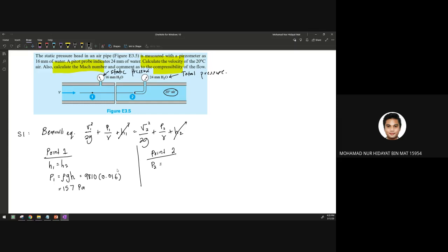So remember that this is a pitot tube meter. When it is a pitot, there is a stagnation at this point. I try to zoom in. This is the tube. Basically the tube is like this. So the water going in this direction suddenly gets stuck at this point. So this becomes static, there will be a stagnation here.